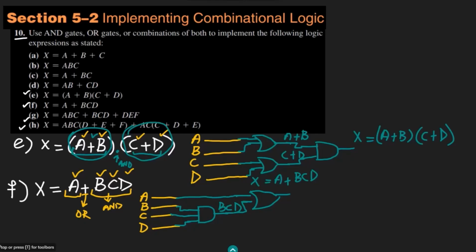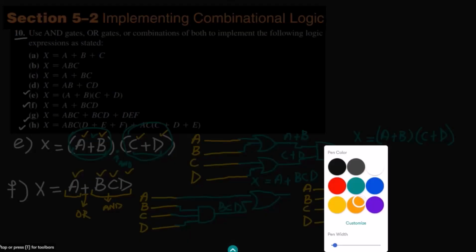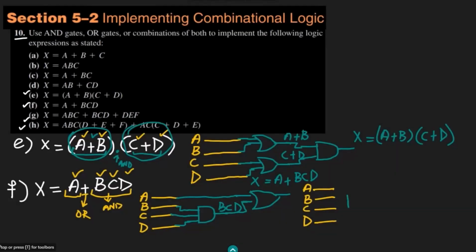This is the first combination, in which I don't have two-input gates. Similarly, for the case when I have only two-input gates, the inputs will be the same, A, B, C, D. Initially B and C will be multiplied together because the only gate I have is of two inputs.